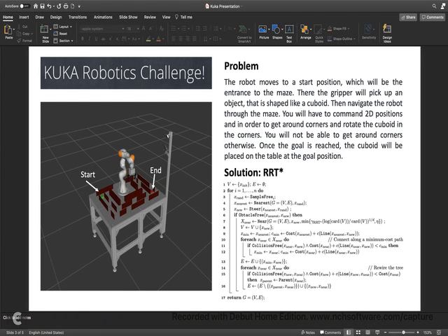The second difference in RRT star is the rewiring of the tree. After the vertex has been connected to the cheapest neighbor, the neighbors are again examined. Neighbors are checked to see if rewiring them to the newly added vertex will make their cost decrease. If the cost does indeed decrease, the neighbor is rewired to the newly added vertex. This feature makes the path smoother, and RRT star actually creates incredibly straight paths. For finding an optimal path, especially in a dense field of obstacles, the structure of RRT star is very useful.